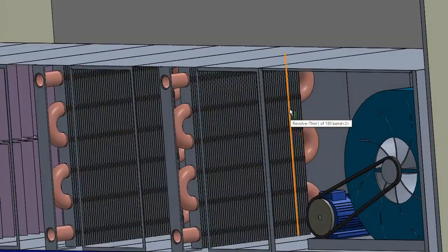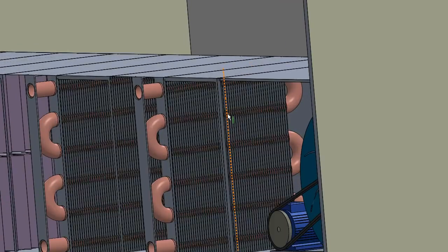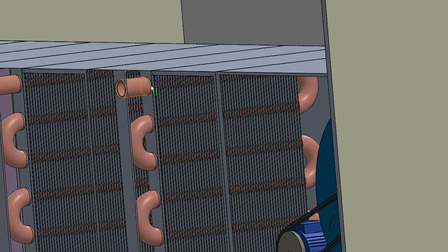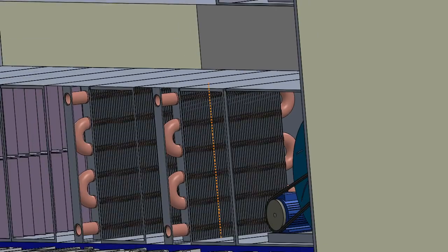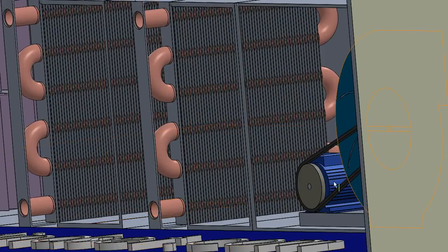But as you should be able to see here, the coil is configured so the pipe inside here runs in this configuration all the way around until it, well, in fact it runs the other way, but same difference, until it exits. So the pipe is going all the way through there, and inside there is the heated or cooled water, and maybe steam. You could have steam on the hot side as well, on the heating coil.